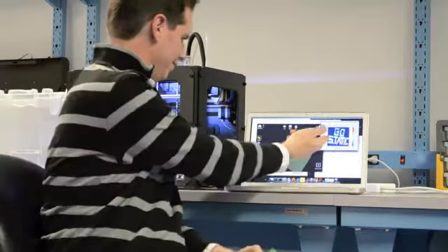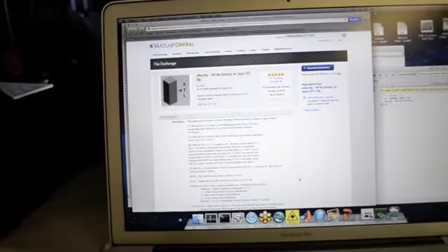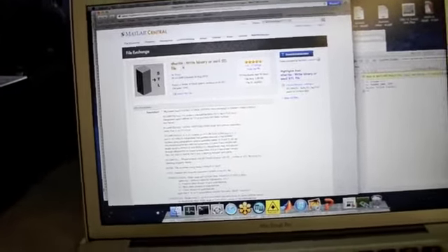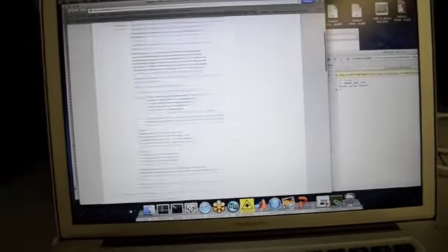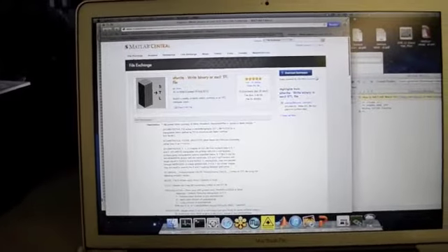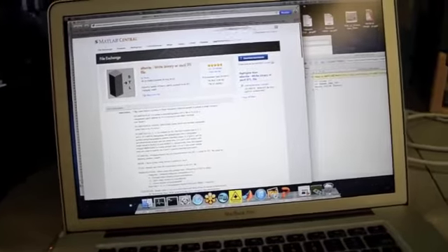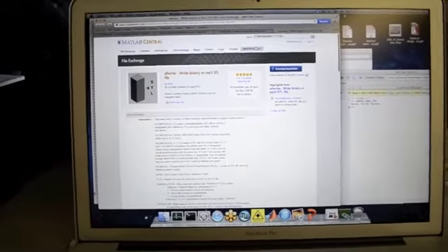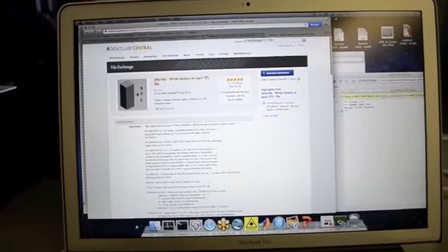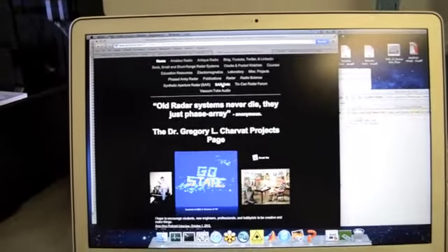Today I'm going to show you how to print synthetic aperture radar imagery on a MakerBot. I found this really cool function on the MATLAB File Exchange called STL-Write, and what it does is it allows you to take a MATLAB intensity plot and output it as a .stl file, which can be read into the MakerBot MakerWare software. And from there you can print a 3D image. So I decided to try it on some of my synthetic aperture radar data.